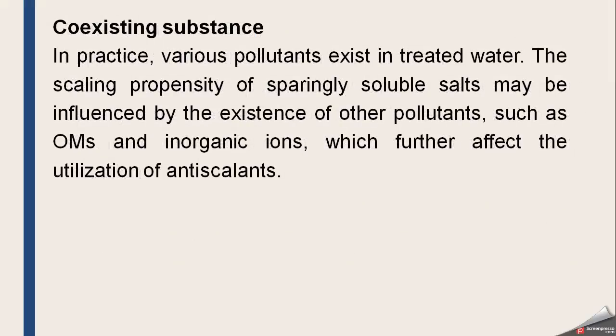Another effect is coexisting substances, that is, the existence of other impurities. There are a lot of impurities in water, and the scaling propensity of sparingly soluble salts, which are less soluble in water, may be influenced by the existence of other pollutants like organic matter and inorganic ions, which further affect the utilization of antiscalants.